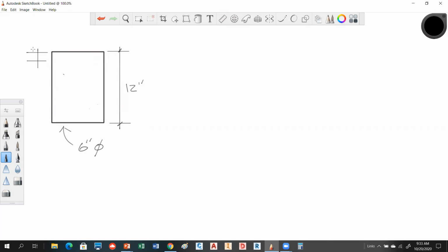They tell us that this thing has a small amount of deformation. That deformation was measurable, but it's really small, 0.001 inch, okay? And because this is concrete, you know that the E, if you look in a chart, or he gives it to you actually, is 3 times 10 to the 6th PSI. Okay, so that's our amount. So we want to know what is the P, the amount of force that will cause deformation to be 0.001.